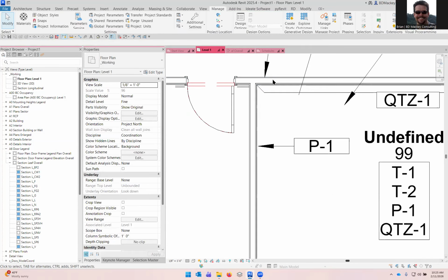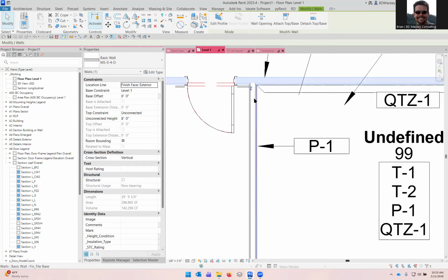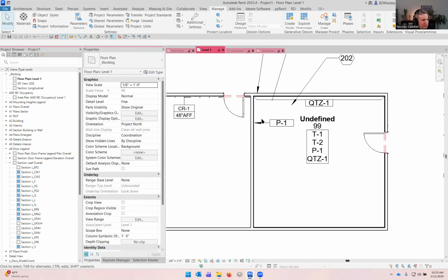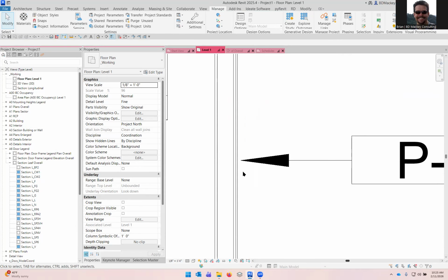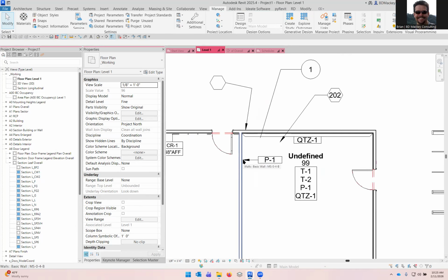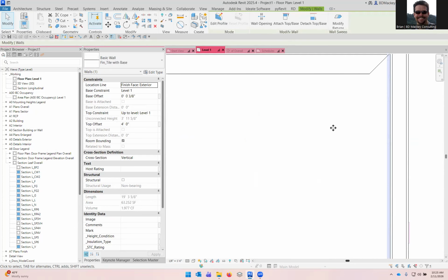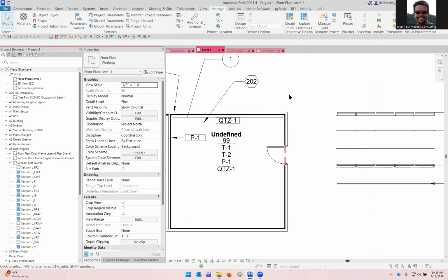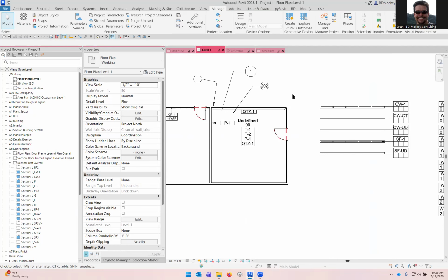Yeah. I'm not a big fan of the paint tool because then you have to split the wall here. Then somebody does something to the wall and the split moves. And now you've got half of it painted and not the other half. Yeah. Not a big fan of the paint tool. So I have clients who literally model a 32nd inch thick wall, and they model all the finishes. They're like, well, if it's a tile wall, we model the tile wall.